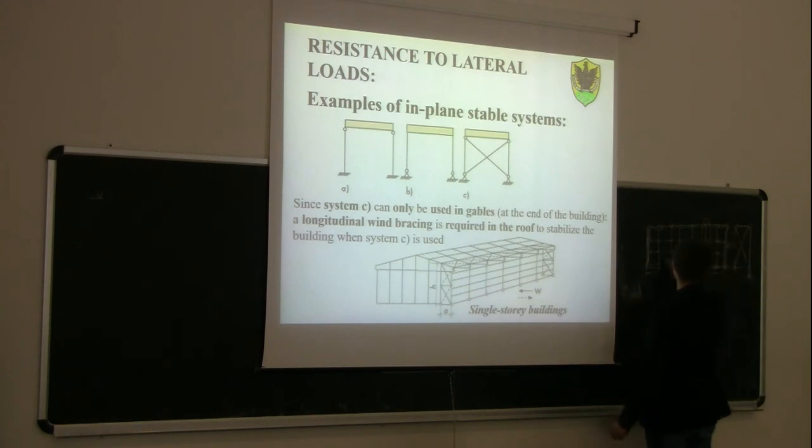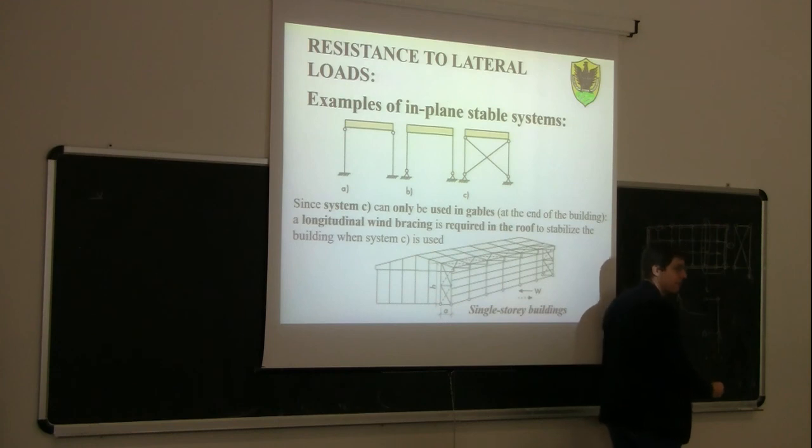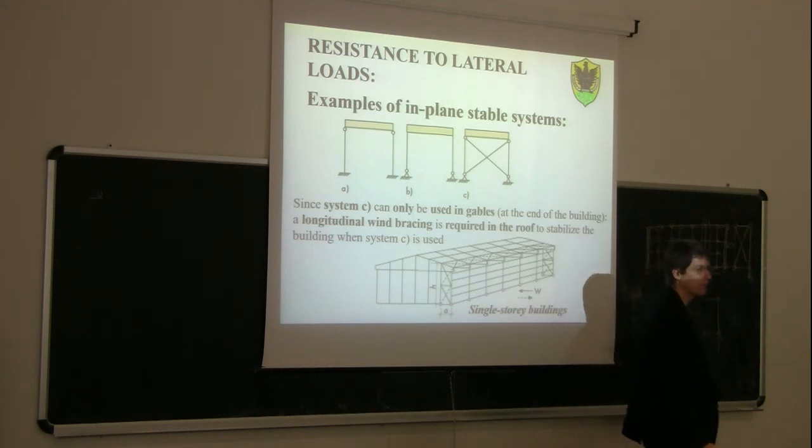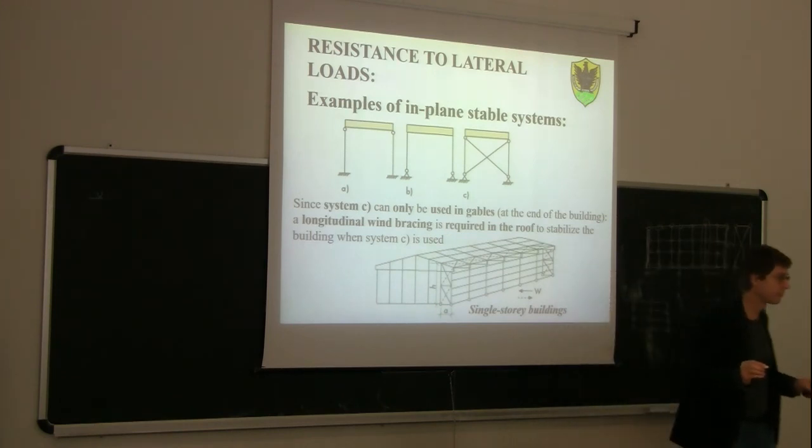Yeah. So now, for the sake of simplicity, I look at a simpler system like this. Okay? So this is braced, this is braced, this is unbraced. Just for the sake of simplicity. If I push here, what's going to happen? Sorry, I just missed one purlin here and one purlin here. If I push here, how is this going to deform? Is it able to transfer this force here or here? This purlin is an infinitely rigid purlin.